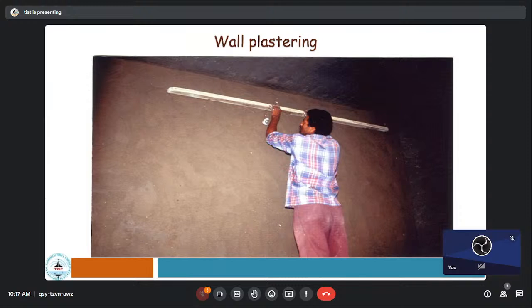So how can you check whether there is a bulge? Whether there is an irregularity of the structure, irregularity in the plastering. How can you find out? Night time is very easy. Switch on all the lights. Okay. Go with the torch. Place the torch very nearby your wall. Light it. You will find all sorts of undulations. Go and see.